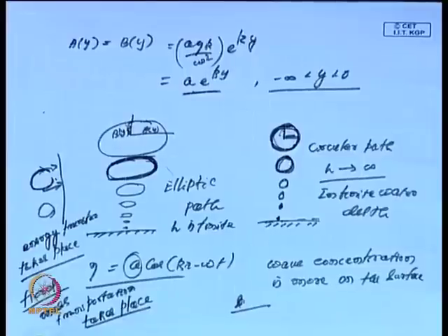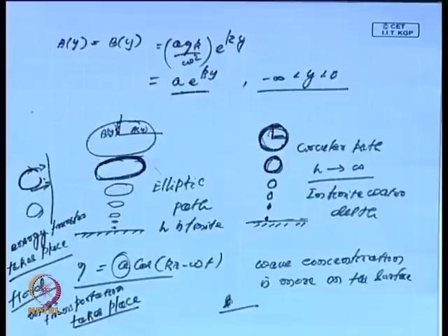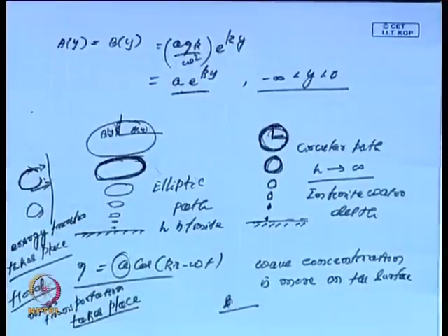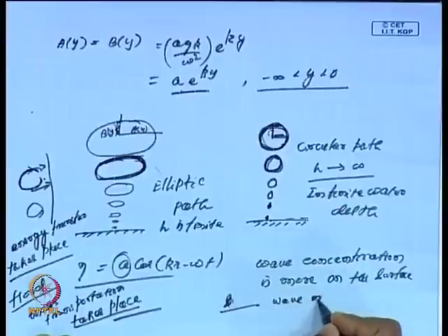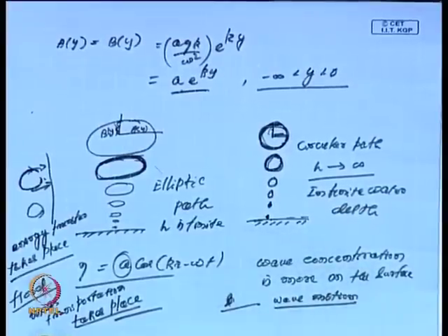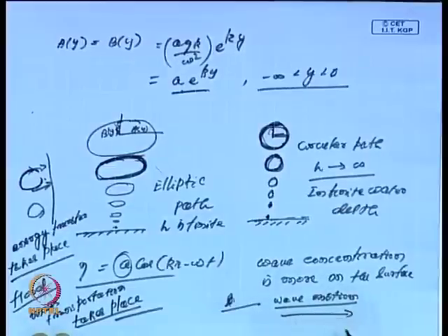So in energy transfer, particularly in the case of waves in the ocean in general, where we have the situation of wave propagation only, there is no transfer of mass. On the other hand, when there is a transfer of mass from one point to another, the particle changes its position before the complete cycle is formed, and in the process the particle changes its mean position. So no closed path is formed, and that is the basic difference between wave motion in a sea without mass transportation and wave motion with mass transfer. This is one of the very important points to note.